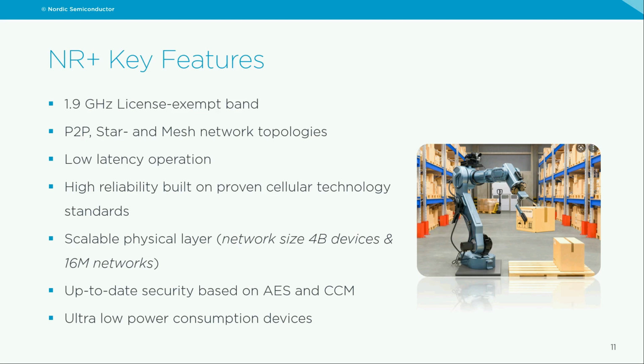And NR Plus is designed on radio level so that you can really build very low power devices. We do not have capacity in this first webinar to talk in detail about low power, but thinking about a very low power sensor node that wakes up now and then to send a little bit of sensor data over an NR Plus network, you can build devices that achieve an average power consumption below 10 microamps, as you also do with other radio technologies today.